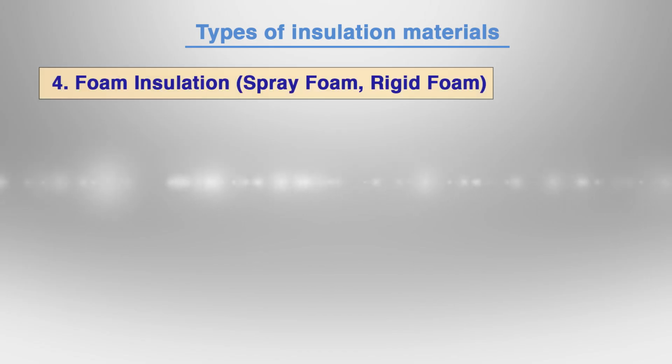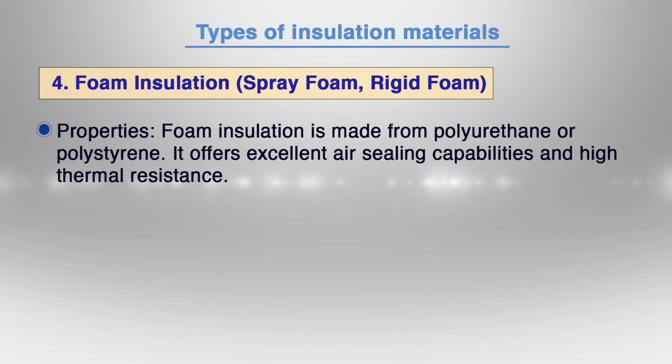Fourth one is foam insulation. It is spray foam or rigid foam. It also has some properties. Foam insulation is made from polyethylene or polyether. It offers excellent air sealing capability and high thermal resistance.